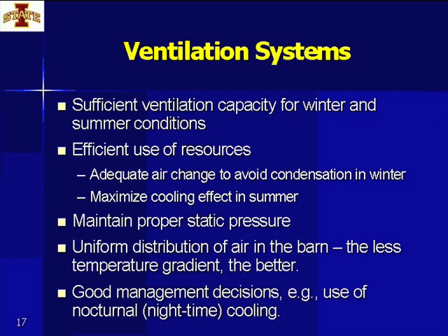All right, moving on to ventilation systems. First, we have to make sure we have enough ventilation capacity to cover year-round requirements. Secondly, once we have that, how do we efficiently use our resources? Obviously, we need proper air change to avoid condensation in winter. Larry touched on proper insulation being important, but once you have that, you still have to have an adequate amount of ventilation to move that moisture out of the barn. Last winter, quite a few folks experienced condensation issues, which were caused by lack of minimum ventilation.